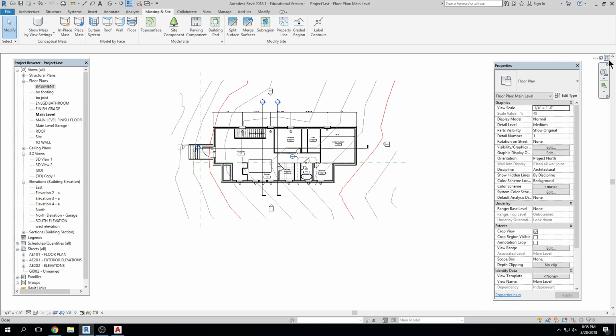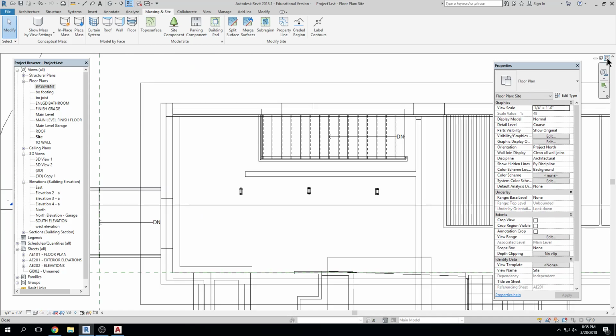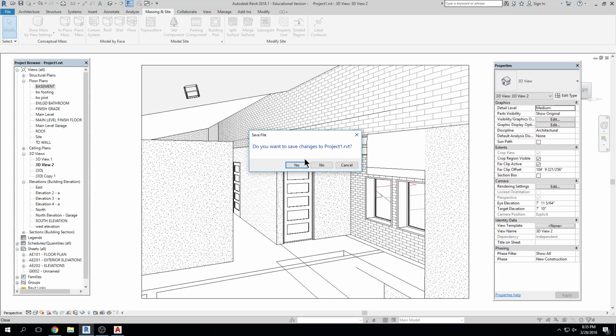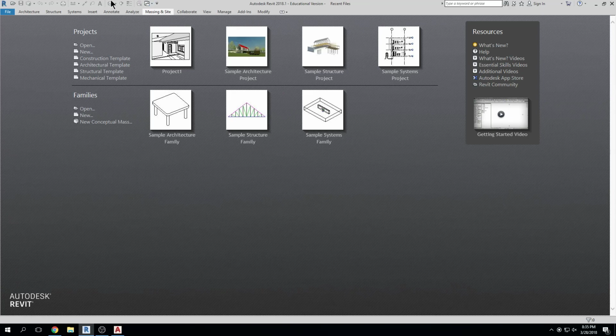Speaking of which, should we get going on that a little bit? Okay. I've got a quick question. I'm trying to do the boundary line and get rid of the dirt in there. And every time I try to get on it, it intersects lines or doesn't connect. So I would just continue to draw and then use trim to trim it out. Yeah, that'll be okay. That's how Revit kind of functions, honestly. It doesn't quite always get exactly where you want it to go.